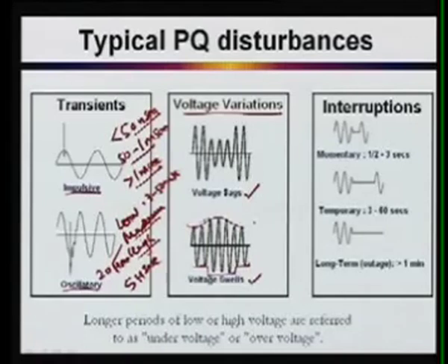Let us come to the first voltage sag here. Similarly, here the voltage was this magnitude in the steady state, and suddenly the voltage is reduced and then it is again following its normal voltage. So this is known as the voltage dip. Again, this voltage dip is categorized in three categories. One is instantaneous, another is momentary, and the third one is temporary voltage dip.